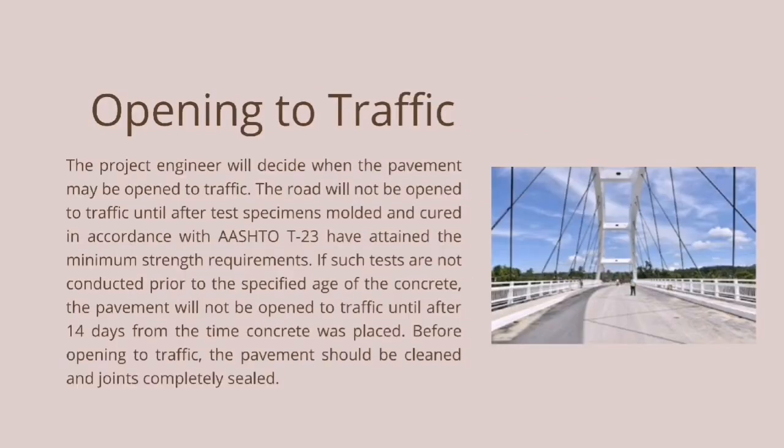And lastly, opening to traffic. The project engineer will decide when the pavement may be open to traffic. The road will not be open to traffic until after test specimens molded and cured in accordance with AASHTO T23 have attained the minimum strength requirements.